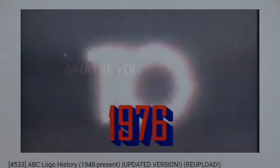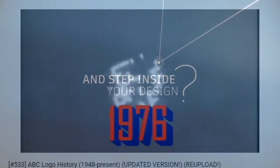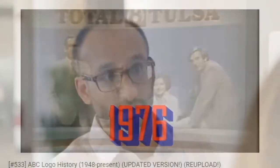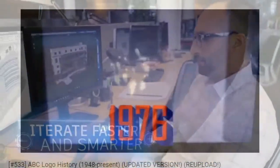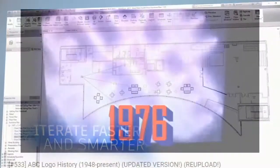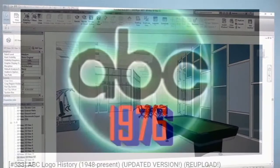One of the easiest ways to divide a floor surface for thin finishes is to use the split face and paint tools. This method will require a floor to be modeled and an appropriate material to be defined with at least a surface pattern. You can schedule finishes applied with the paint tool only through material takeoff schedules.